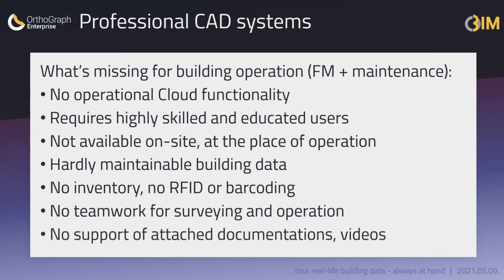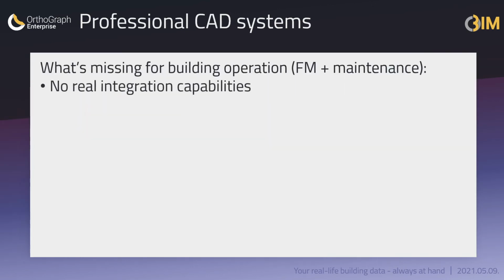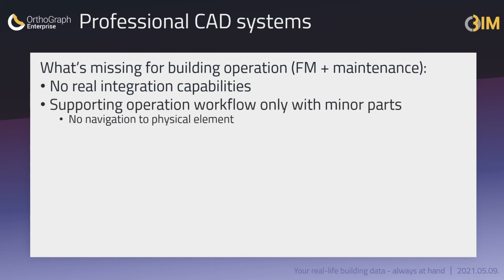Certainly, it wouldn't make any sense to store maintenance data, manuals, videos in a model made for planning and probably for construction, so that's also not available in CAD systems. CAD systems are not built on databases. Integration with external systems is mainly made on file basis or sometimes using built-in applets to the CAD systems, but ERP systems have never been a target of CAD systems. This also means that accessing data by the on-site worker communicating about exact elements of the BIM is not available.